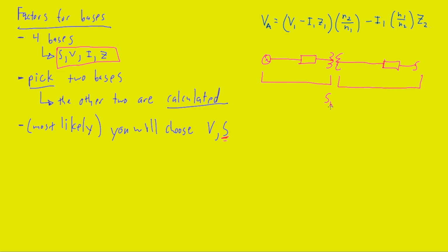In relatively ideal conditions, we can understand that a power base set for this could actually be just one for both sections. We could very easily imagine voltage, current, and impedance changing, but power isn't really altered by the conversion at the transformer. We have voltage changing or some other factor, but power can be the same on both sides of the transformer.